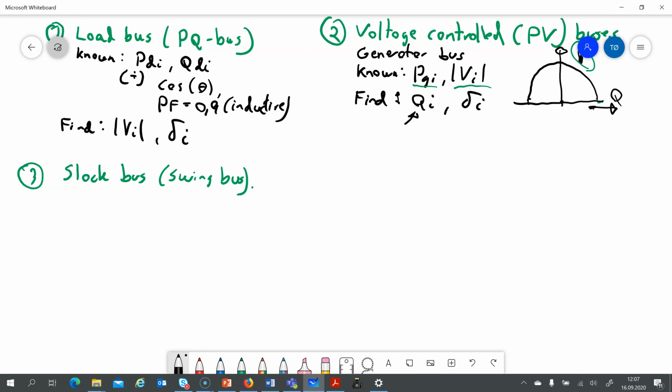So in here we also define something, and one thing is that we typically define the voltage and the angle of that bus. One classic way is to put this as a 0 angle. Then this becomes like a reference value.